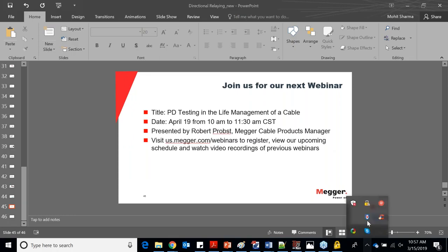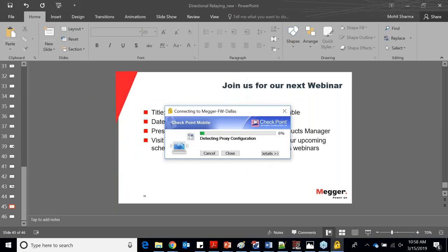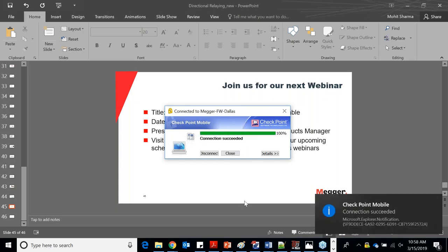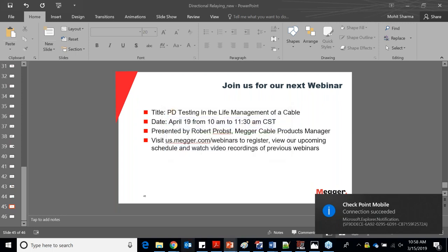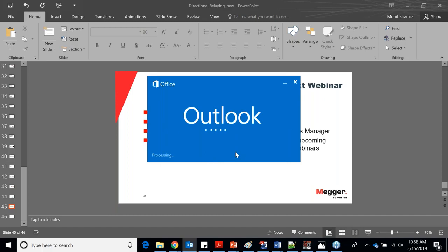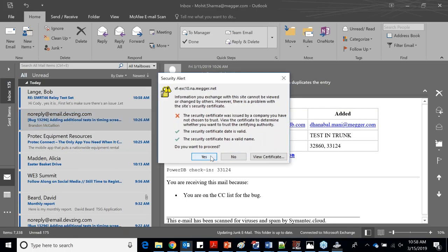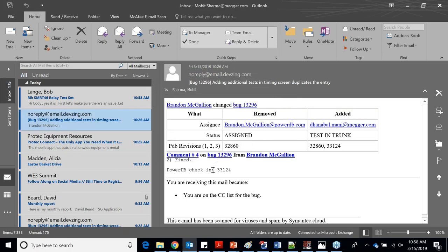First one we have on the list is: on a high resistance grounded system, the capacitance current is the design factor, it flows from line to ground and is balanced. But during a single line to ground fault on the network, this capacitance current changes its direction and flows from ground to line, because the total current now is the vector addition of NGR current plus this reverse capacitance current. Is there any way that we can have ground directional protection 67N using a zero sequence CT?